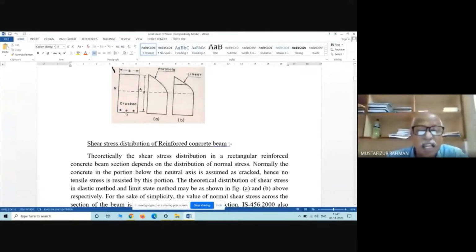So here I had shown reinforcement at bottom, no reinforcement at top. It will not be easier to keep the concrete in this way. So to keep this section, although we do not require any reinforcement here, we will provide reinforcement here.